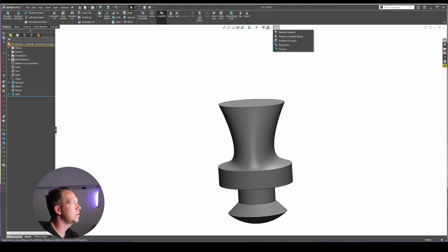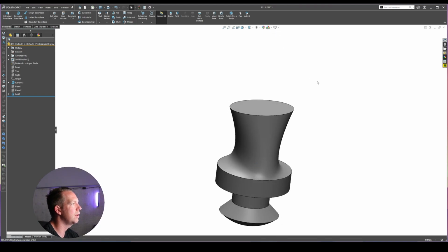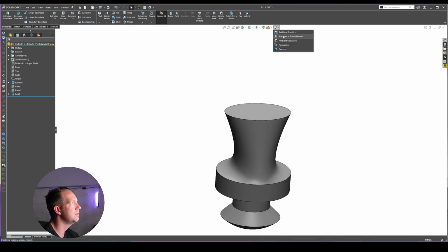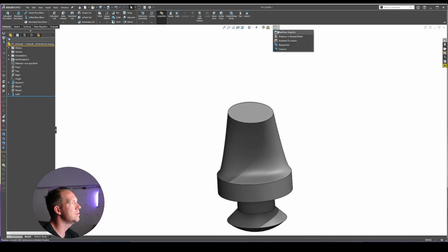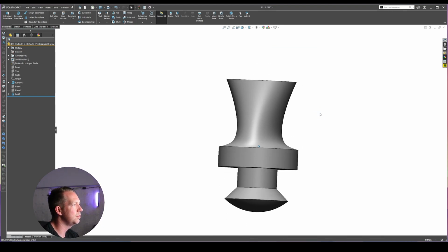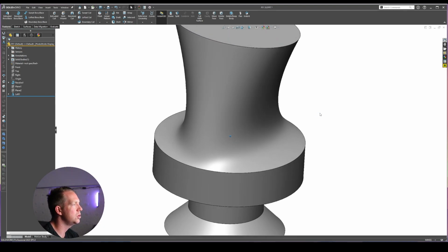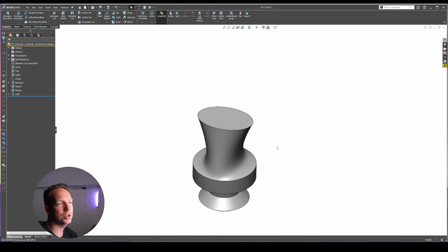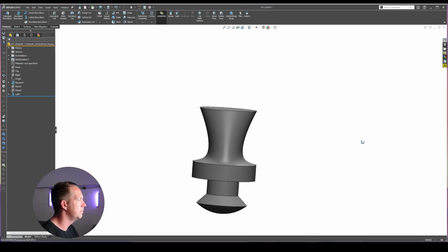Now, depending on your SolidWorks settings, whether you've got real view graphics turned on or material as your default, you might get different appearances. I like to work with none of these appearance tools on, so that I'm just getting the same generic view while I'm working with my geometry. I will change those settings later, but if I need to visualize anything like surfaces, I'm often exporting to Keyshot and doing some proper visualization work. So that's our loft.